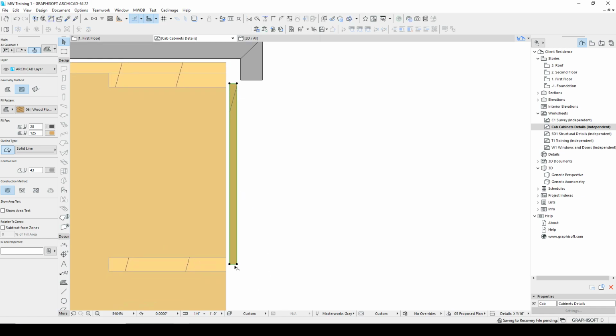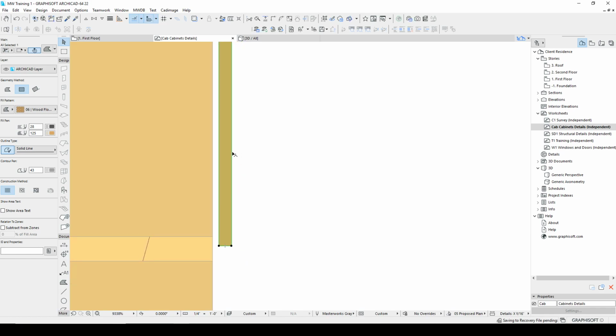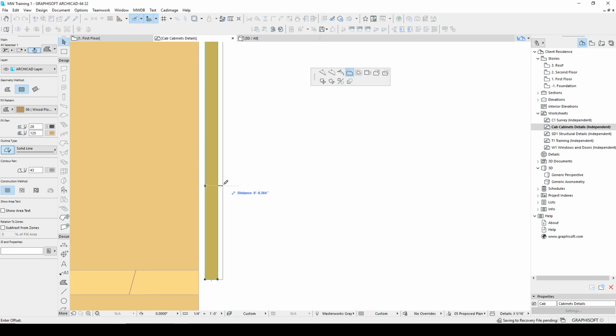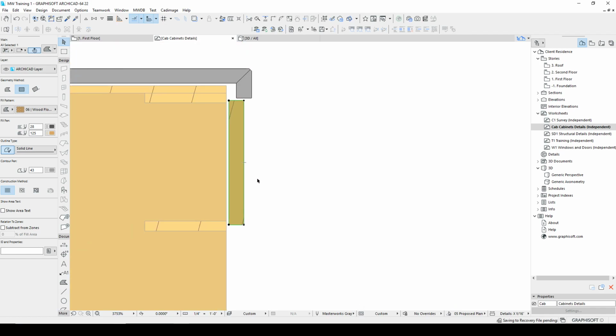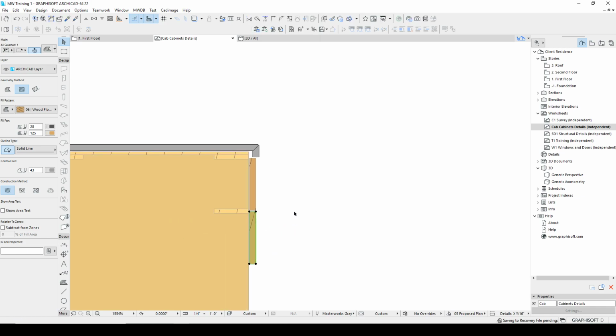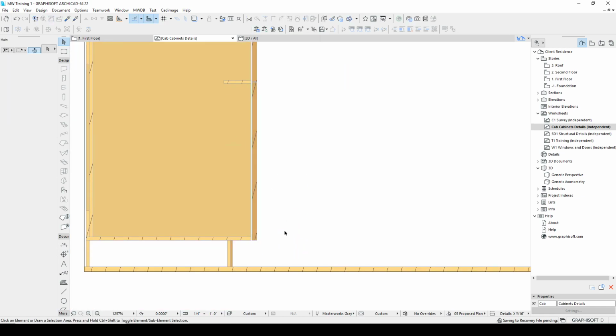That's to the center, and often then you'd go 0.0625, 1/16th over, and we'll make this 3/4 of an inch. Again, I used Shift Alt to move my reference point. There's my front. I can copy this down here, F9 again, or F5, move it down 1/8 of an inch, and then drag this all the way to the bottom of the cabinet.